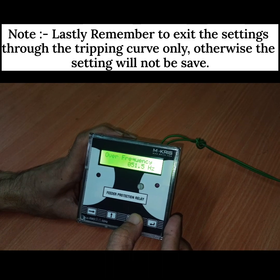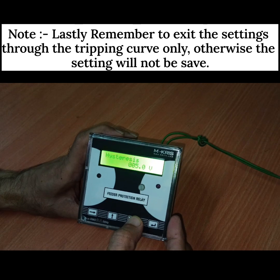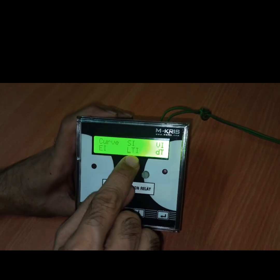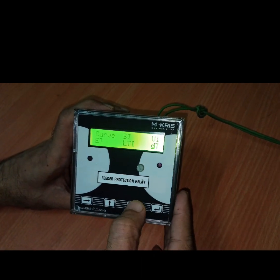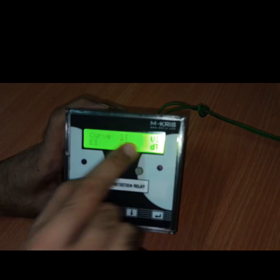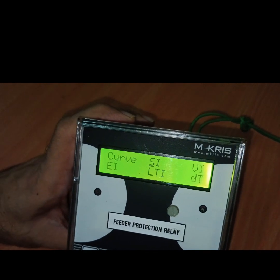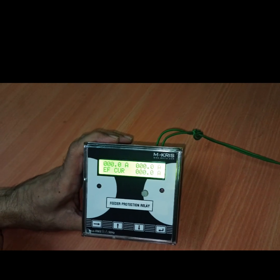And lastly, we have to remember that we have to exit the settings through the tripping curve only, otherwise the settings will not be saved. And let us look at how this is selected. Again we will press this button, and right now the LTI curve is selected. This can be changed by pressing the up or down button. So let's say we select the standard inverse curve. We can see this small horizontal line at the bottom. So this curve is chosen, and now we can save this setting and exit the menu settings.